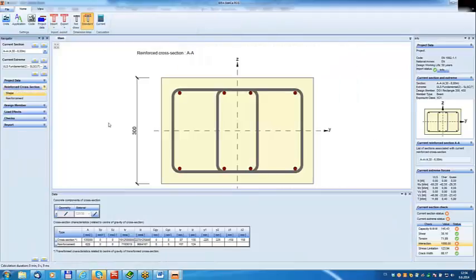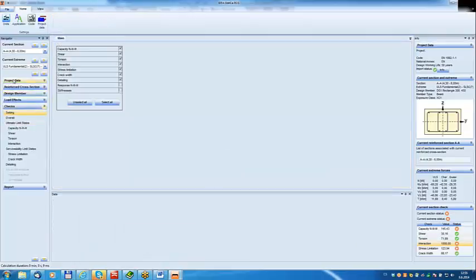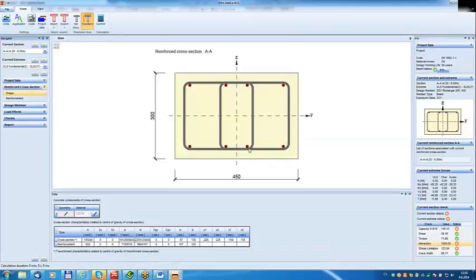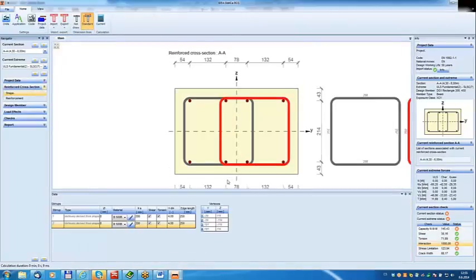So if I go back, I wanted to show also this. I already put 250 millimeters overlap here of this reinforcement. So my detailing did not appear because it is satisfactory. If I change this, for example, I will have to change the stirrup. I will not do it.